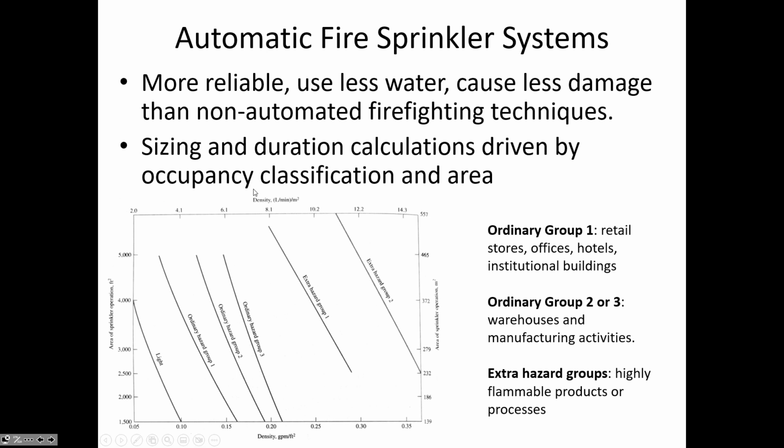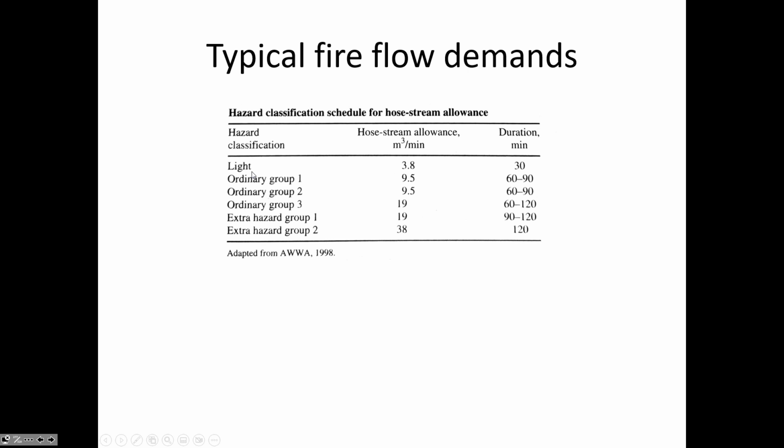So it's relatively straightforward, but what's a little bit more complicated is ensuring that there is enough duration of protection available. Compared to the usual demand for water, a fire has the potential of completely exhausting the elevated water storage tank that is often used to provide pressure, especially in places that are relatively flat and don't have a gigantic reservoir up on the hill around the outside of town. Sometimes small towns will have an elevated